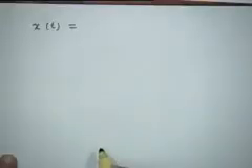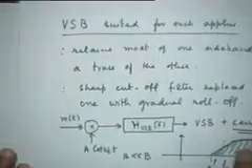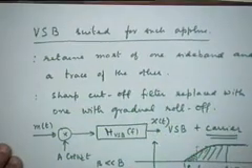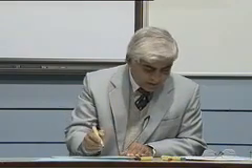What we would like to see is what is the nature of the modulated signal x(t), where x(t) I am defining once again to be this signal here, right? So we will soon see. In any case, it's obvious that x(t) is a narrowband signal still. It's a bandpass signal. There is a center frequency, carrier frequency, and there is a spectrum around the carrier.